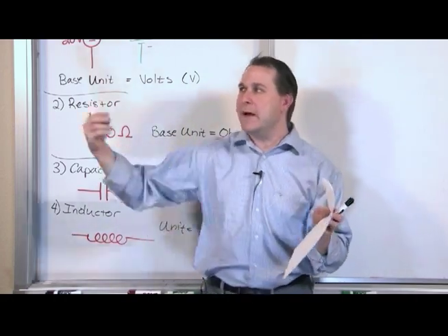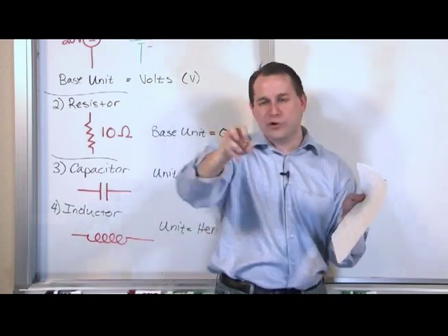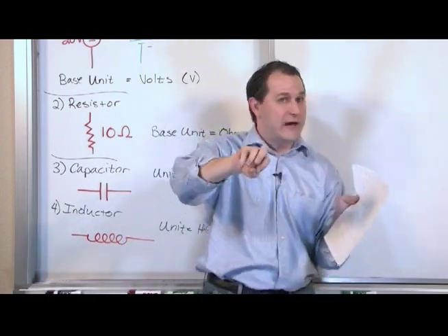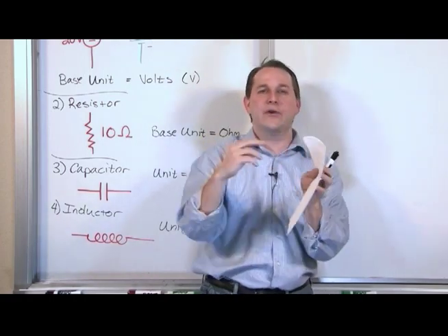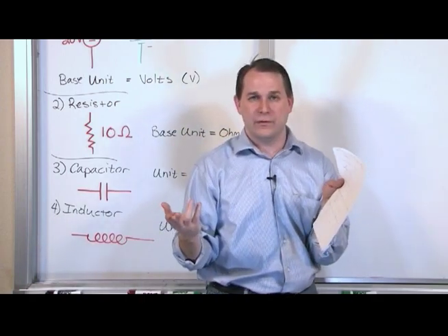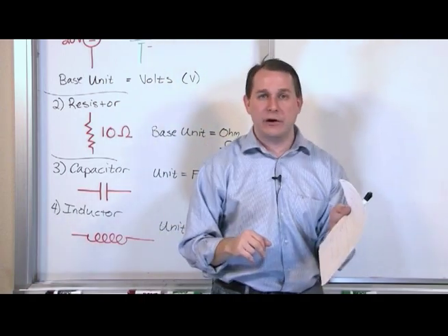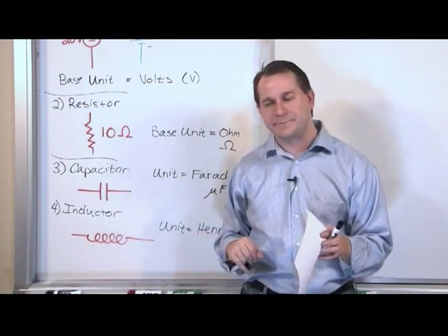So you can think about it like the wave comes in, hits the antenna, and goes to these capacitors and inductances. Of course, you can tune the knob and change the value of this capacitance, and when you do that, you're changing the way the circuit behaves so that the frequency you want, the radio station you want to listen to, is the one that gets sent to the speaker because of this perfect dance of energy between the capacitor and the inductor.